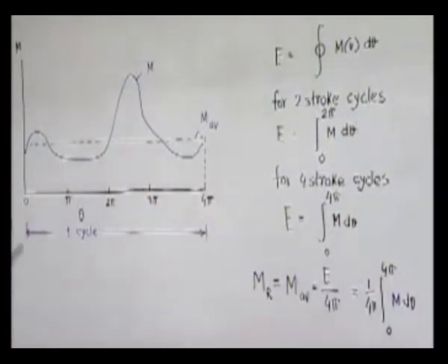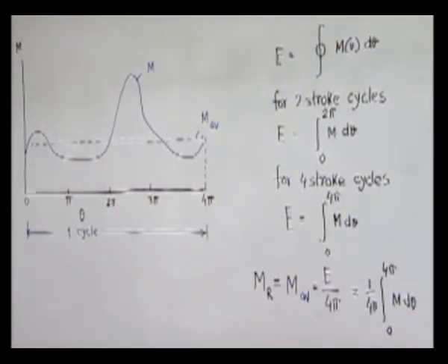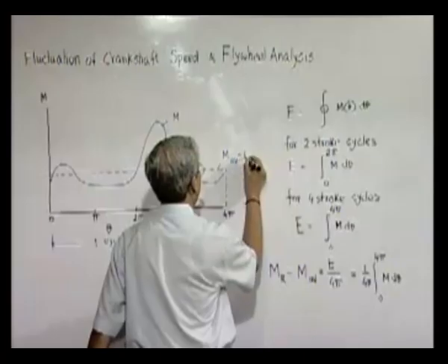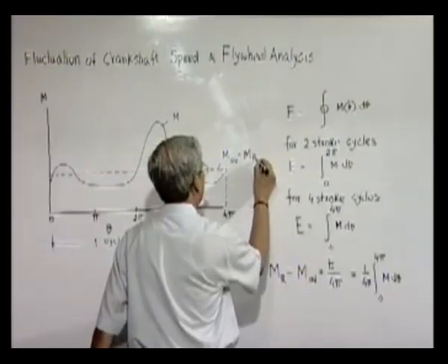So once we know the turning moment diagram, it is possible for us to find out the average moment, which happens to be the load or the resisting moment.